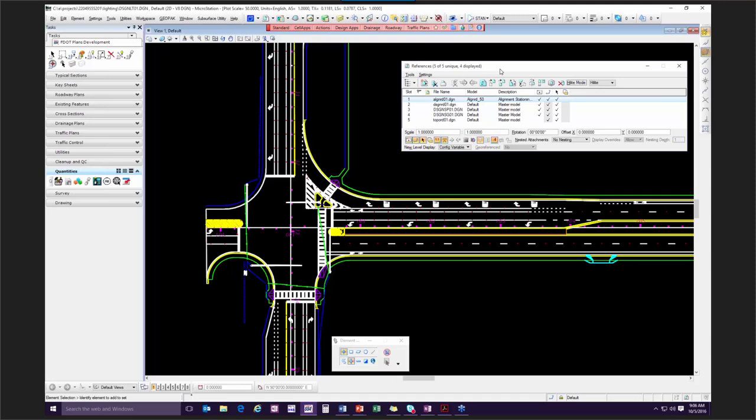The topo, if you look in the plans preparation manual, is kind of optional. You would show it if you need it, to make sure there aren't any conflicts, but you have to look at, I think it is chapter 25 in the plans preparation manual, which tells you what is required in your plans. For the criteria for the design, you can look at chapter 7 in the PPM volume 1, as well as we have some design standards out there for our light poles, our high mast lighting, etc.